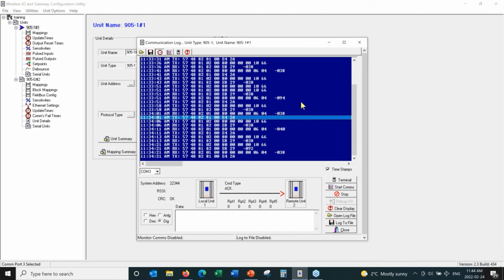If we had clear line of sight over 1 mile, no trees in the path, we would expect the RSSI probably to be about -70, rock steady. So it might bounce around -68, -71, but it's going to be within 2 or 3 dB consistently. There might be the odd case where we get a multipath condition to occur, but it's far less common when there is clear line of sight between 2 locations.